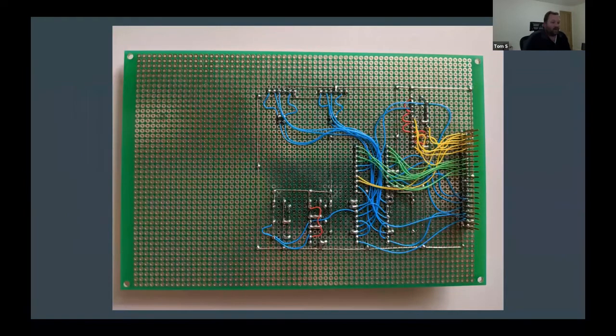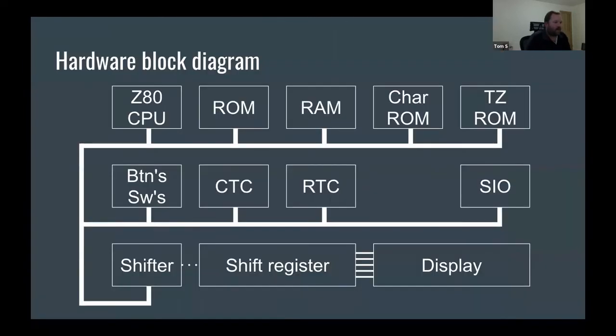And the good thing about using a Z80 family peripheral is that on the back side of this, it's really incredibly simple. Nothing more than a few address lines for decoding the data bus, and most of the signals are going off to the 2 headers where I plug in my FTDI cable. So I think that covers all of the physical hardware.